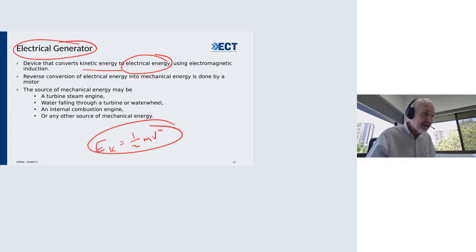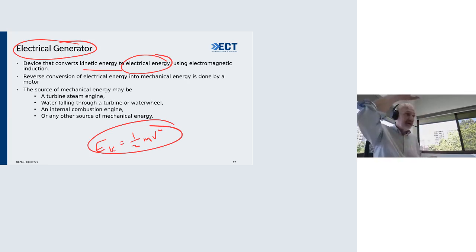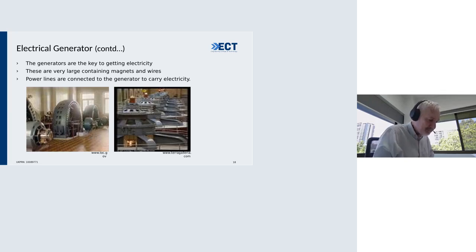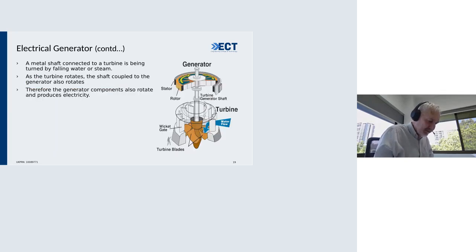One particular installation I had in Cape Town, South Africa, they used to store the energy in a dam on top of a mountain, and then during the night when no one's using power, they used to pump all the water up to the top of the mountain. Then during the day at peak times, winter particularly, you have the turbines operating because you're running the water down from the dam like a storage battery.